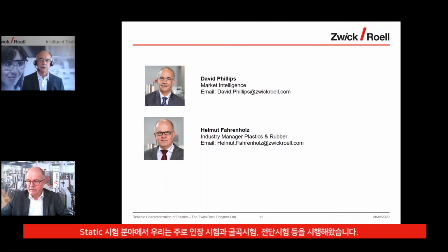Yes, David. In static testing, we mainly see pull and bend, so means tensile test and flexural test, even though there are additional tests, such as, for example, compression or even shear testing. So you carry out these tensile tests according to ASTM D638 or ISO 527 Part 2, and the flexural test is D790 or ISO 178. For such tests, in most of the cases, we can use a 10 kN load frame.